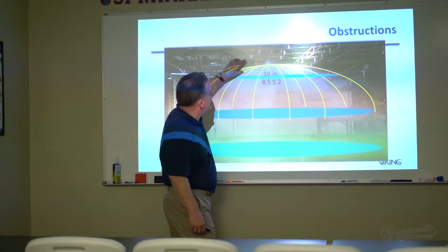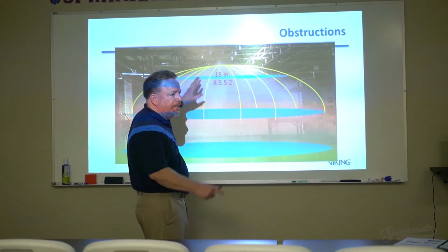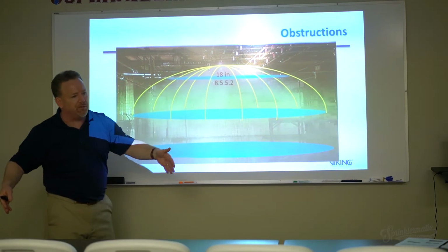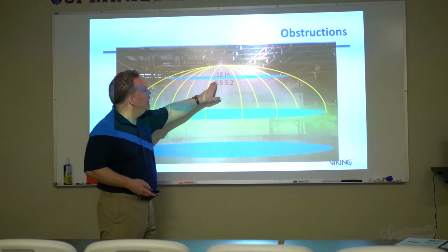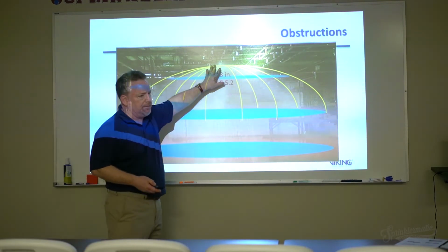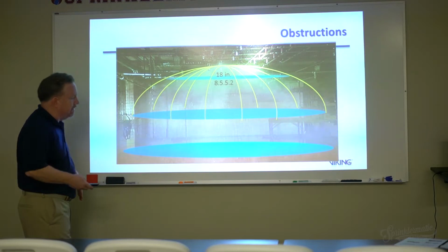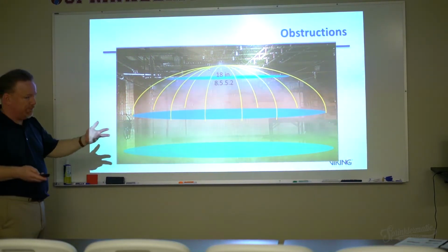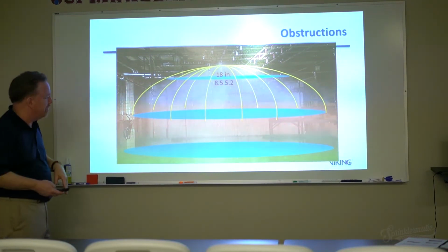In other words, any obstruction, beam, light fixture, anything up in this space is going to obstruct the spray pattern from even developing. Okay? So 8.5.5.2 says that you're going to have to pay attention to these. Not that they're not going to exist, but we have to have some specific rules on obstructions to spray pattern development.